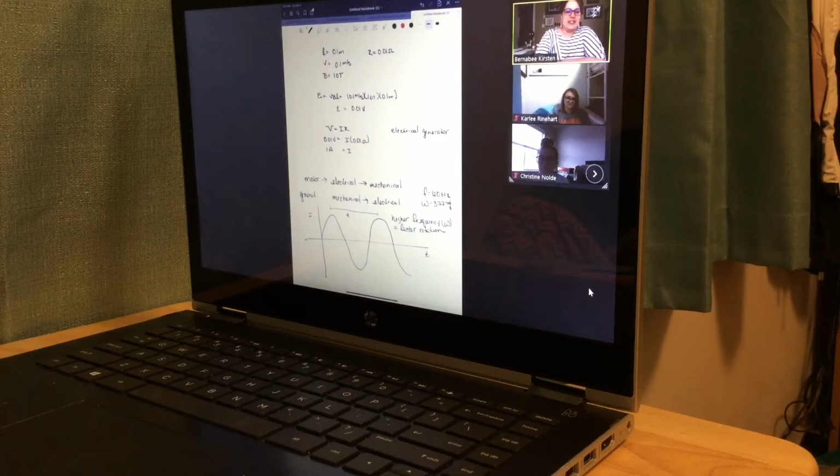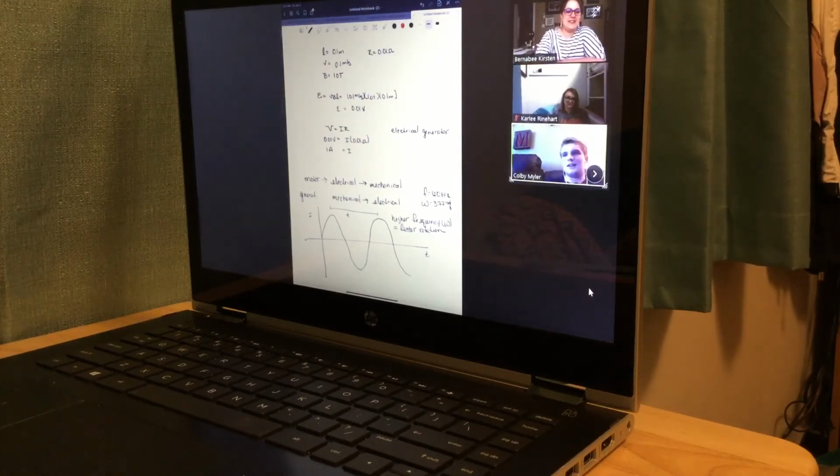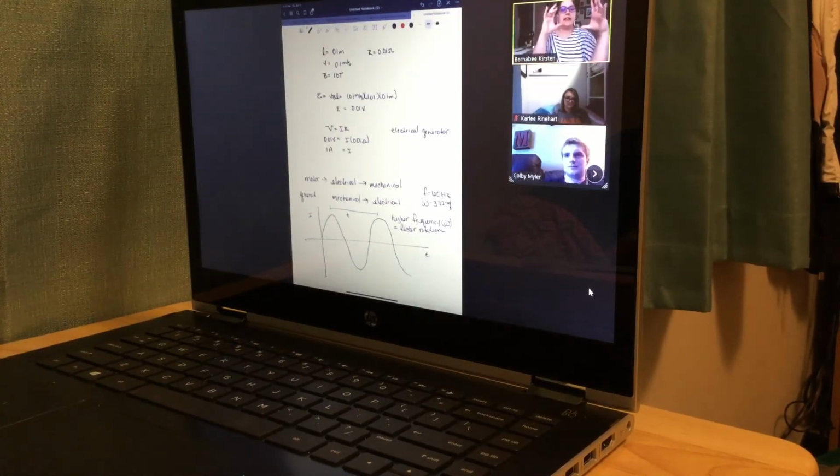All right, there's another question. So where does the magnetic field come from in this generator? It's an external field, so you would probably have to have a secondary system, like an electromagnet that would surround the turbine. Imagine a coil of wire that surrounds it with an independent power source. It doesn't come from within the generator. It's something you also have to supply.